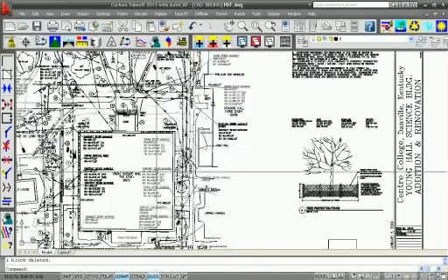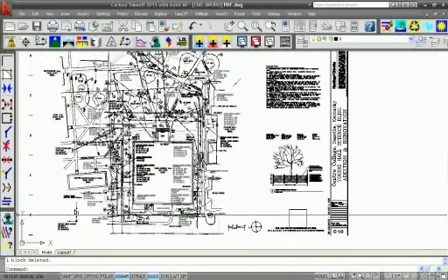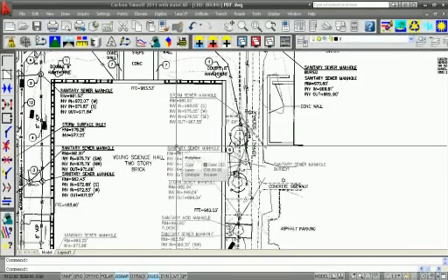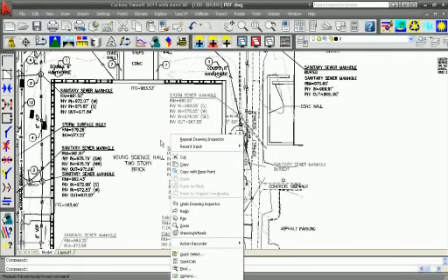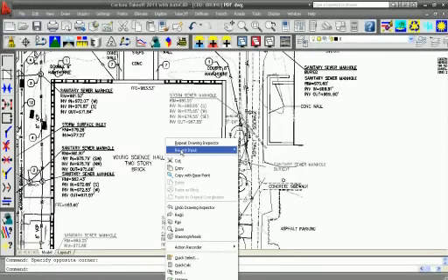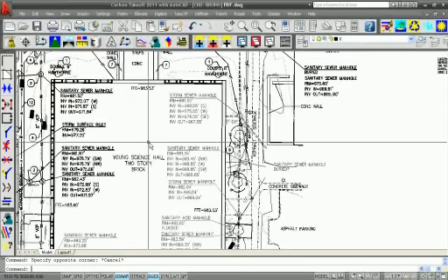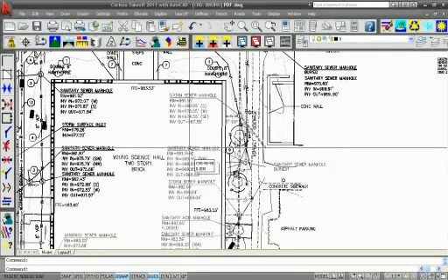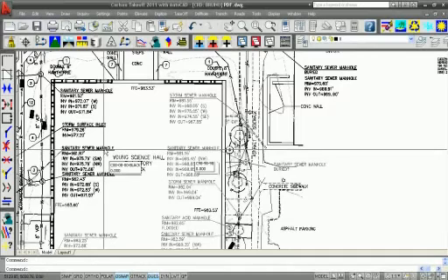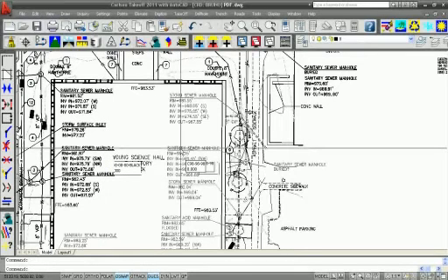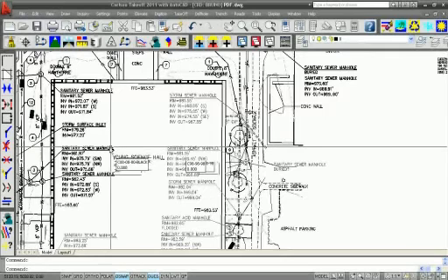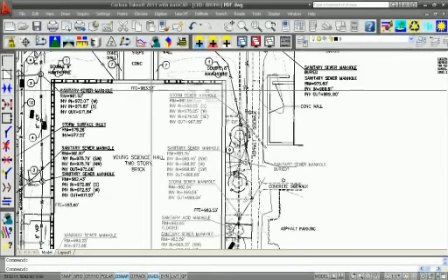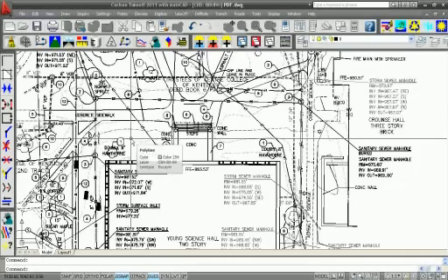I can zoom in on it. And right away, I'll go to Drawing Inspector and go over this line work. And what I have checked for my Drawing Inspector is for it to show me any elevation in the line work, and its layer name. And if I go over here, you can see it's set this to a layer, and this is now on a different layer, black. This is based off of the grayscale. Before, these would all be on the same layer, 0.